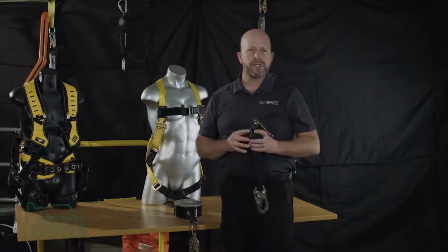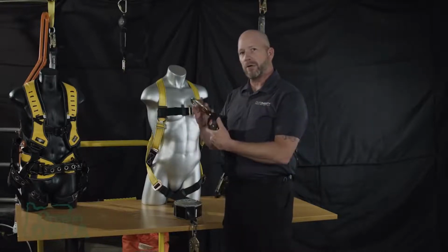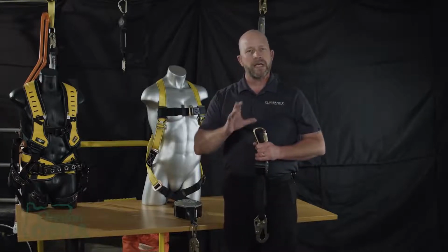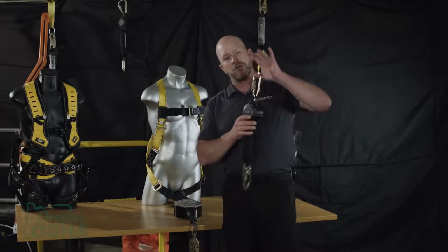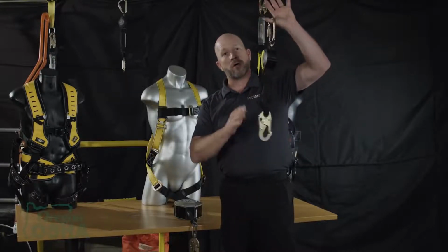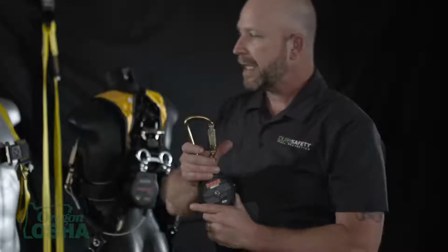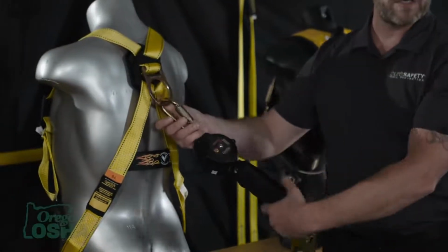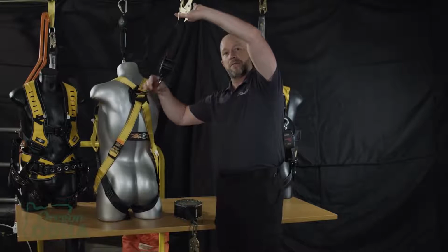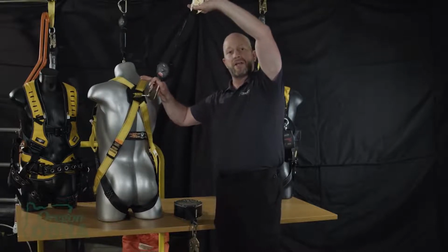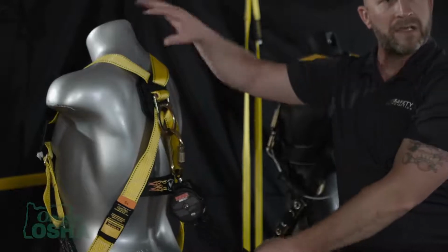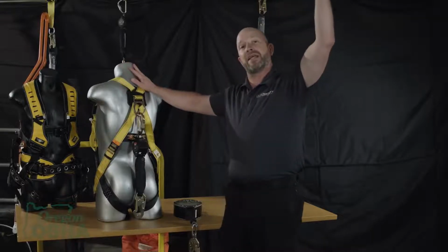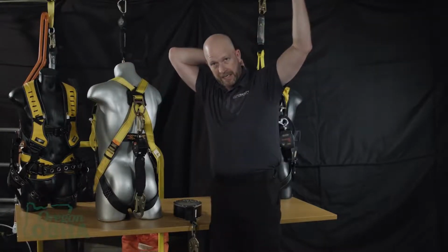retractables, generally speaking, are smaller block retractables or little ones, also commonly known in the market as a PFL or a personal fall limiter. On these, we can go block to the anchor, hook to the worker, or because it's a personal fall limiter, it can be worn in a condition where the block goes to the worker and the hook goes to the anchor. It will still arrest in the same configuration, but the lightweightness of it allows it to be permanently or temporarily affixed to the worker this way, as opposed to having to find the anchor and then attach to your D-ring in that configuration.